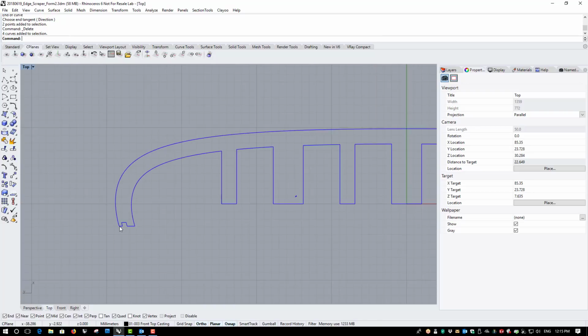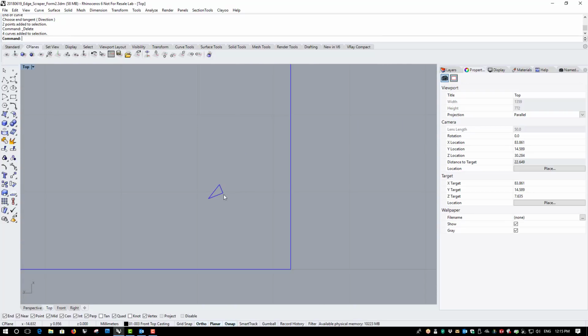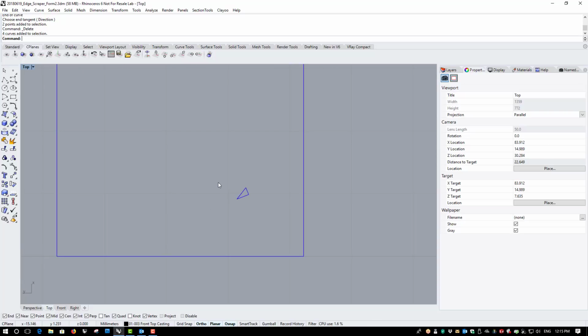The second reason why STL files fail is that the volume may not be manifold because there will be a shard of surface or mesh inside of the main volume. In order to be a valid STL file, there should only be one manifold solid per file.